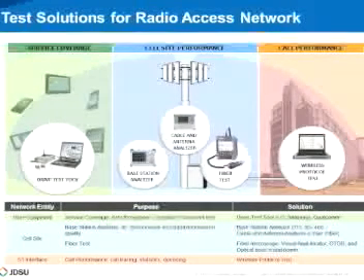But I'm also a big fan of the drive test receiver. Drive test receivers are special purpose, meaning that they have bandpass filters and pre-selectors, which give a much more realistic representation of how the handset or the base station would see the spectrum. This is very important when measuring, but the other key advantage is that a drive test receiver is very useful for doing multiple bands and multiple technologies at the same time. So they're great at multitasking.